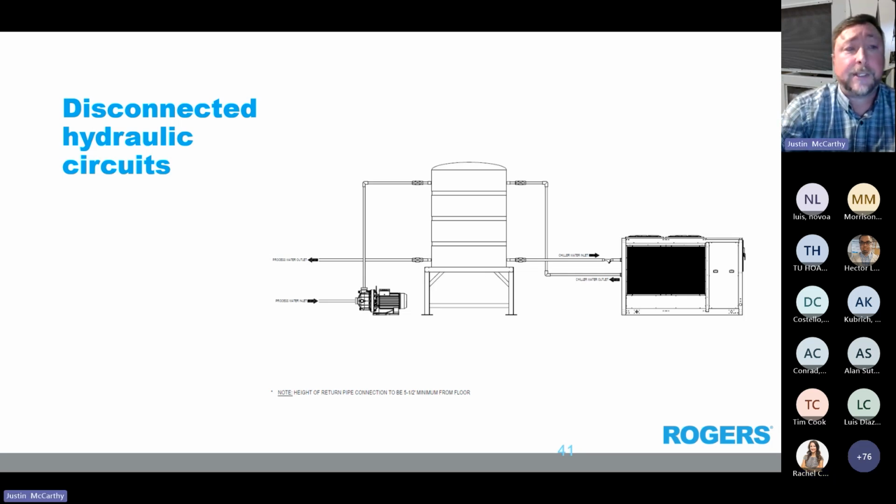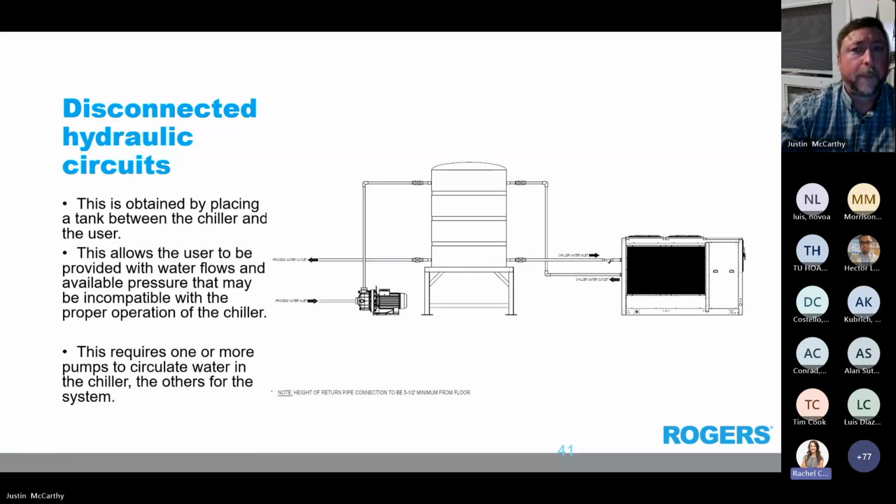So the refrigeration system, most refrigeration or packaged products do not want a higher return water temperature coming back than 87F because it'll overheat the evaporator and it'll cause problems in the refrigeration system. So as a general rule, I pushed it up to 90F on certain ones, depends on the flow variable. But typically anything over, if you're in those temperatures, you should be using a fluid cooler anyway. Great, thank you.